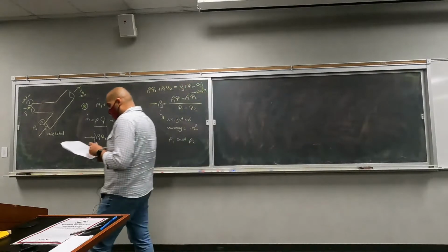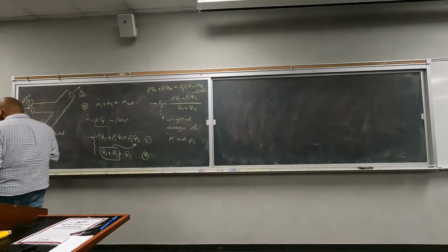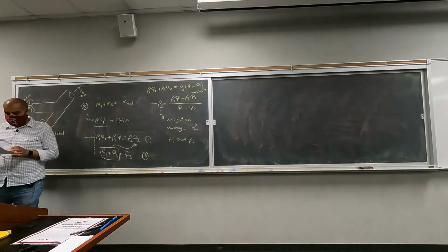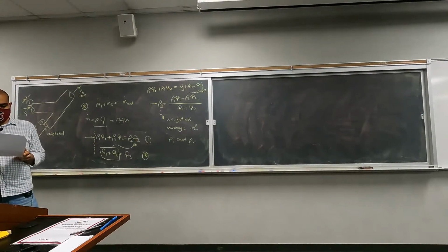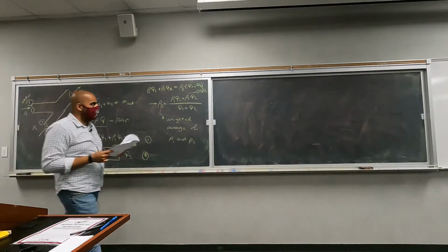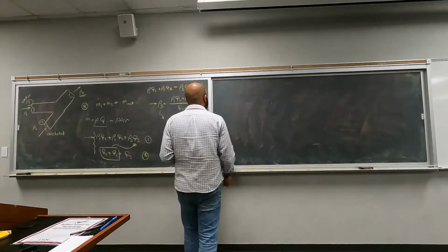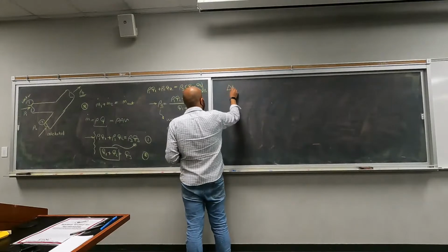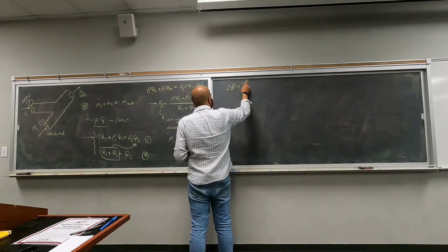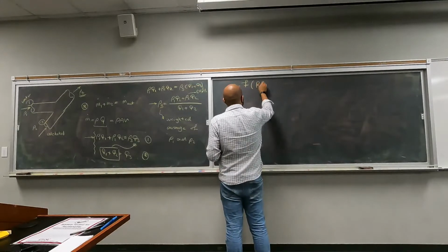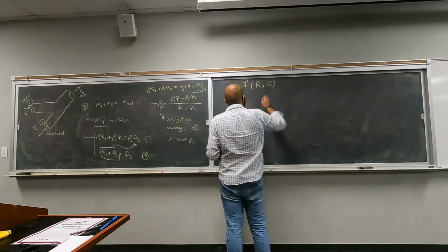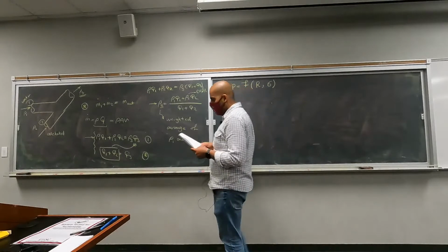Okay. After finding the pi terms, we want to determine the variation in excess pressure if we double the radius or double the surface tension. So delta P, the excess pressure, is a function of R, the bubble radius, and the surface tension, sigma.